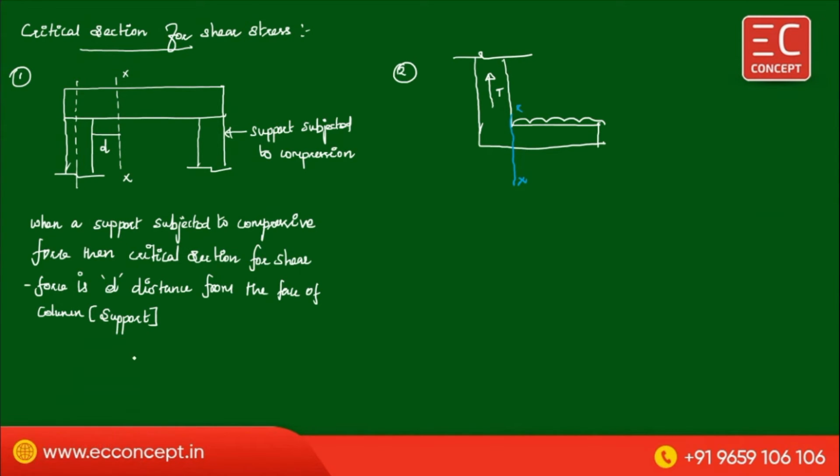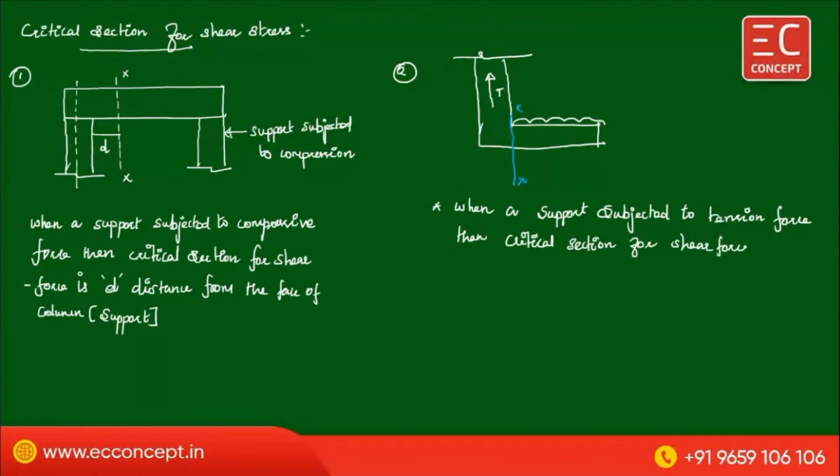Okay, so we can write when a support is subjected to tension force, then critical section for shear force is at the face of the column, or we can say support.